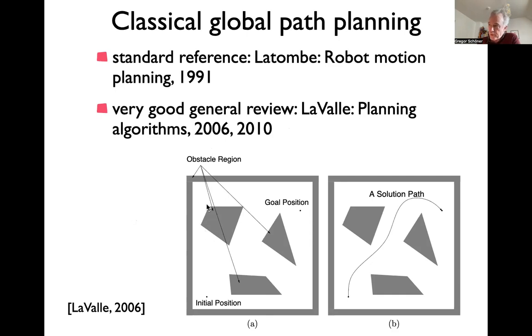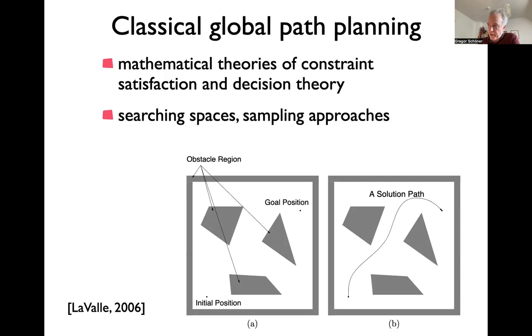So for instance, polygonal worlds, so piecewise linear surfaces in the 2D world. And then your vehicle is also a polygonal system like that. So like a rectangle or some other shape. And then a very typical class is to move toward a target configuration of that vehicle, not just the position, but also its shape, how it fits, while avoiding obstacles. And so that's a special case of much more general problems. And essentially, what people do is frame this as a search problem. You're searching for a path, which is a function in configuration space, or a function of a parameter which you could consider time.